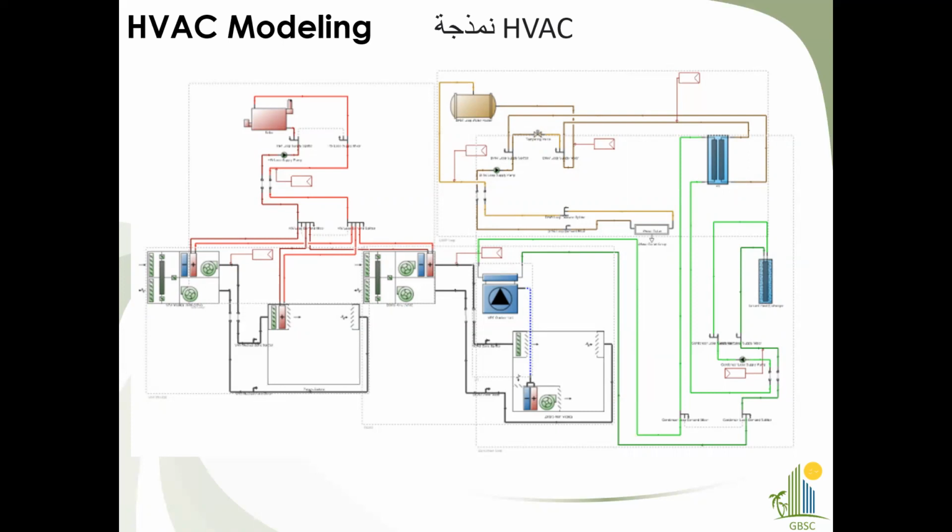It can be modeled, and we have the pre-made modules for most of the possible systems, from radiant system to underfloor air distribution system to VRF and central chilled water system, air source heat pump. So all those things, we don't have to model from scratch. We can do it from scratch, but the basic layout is available within DesignBuilder, and we can use that as a starting point to develop our model further. Then ground source heat pump. So I'll show you how to import those modules and use them within our model.